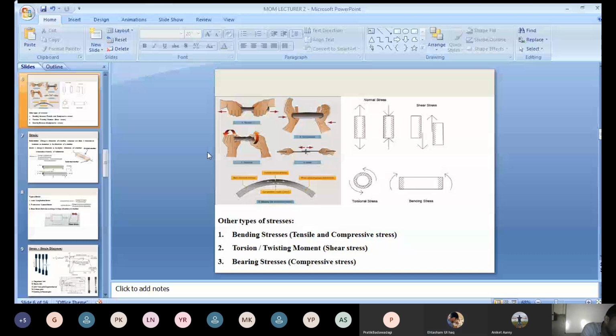Okay. Not there, Anirudh? Grishma? Yes, sir. Give me example. Example for tensile stress is guitar string. Guitar string. Okay, it is not a tensile actually. It is a transverse load. We'll consider as a transverse because we're not applying along the axis. You are applying perpendicular to the axis. That's why called as a transverse load. Later we'll come to that, when it comes to the beams, there's a transverse load.